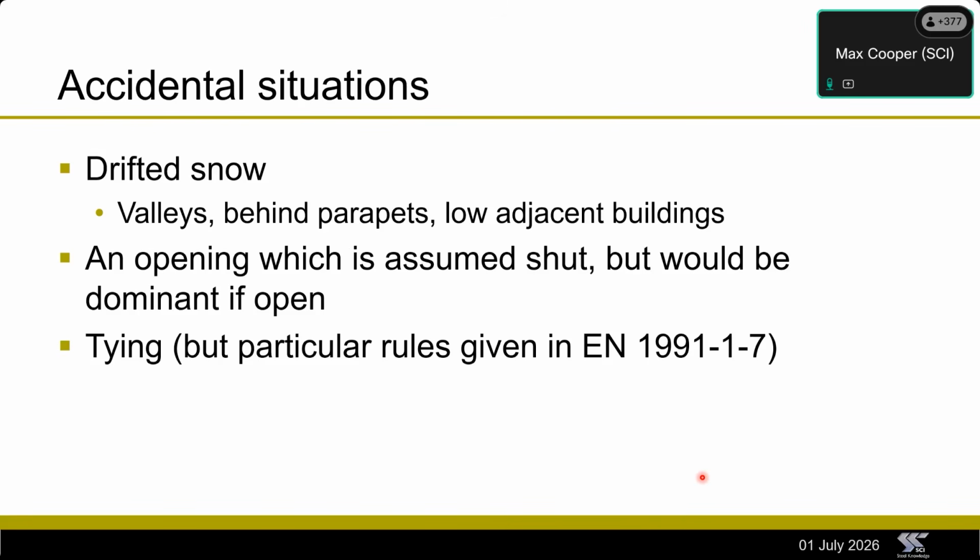So let's just go over what a few of these accidental situations might be, because I think, as I alluded to before, they crop up more often than you might find. There's a few key accidental situations to consider. The first one is drifted snow, and I should highlight that this whole presentation is in accordance with the first generation Eurocode. So some of these things will not be true in a couple of years, and for that I can only apologize for the confusion.